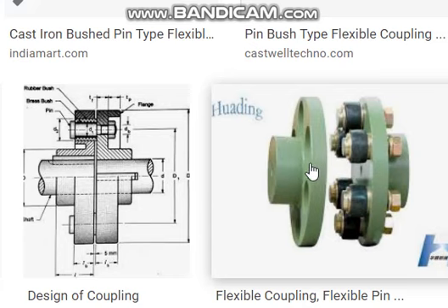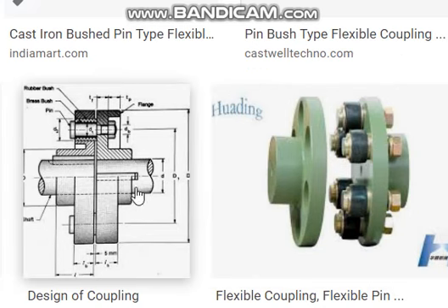This is another flange. In this, holes of larger diameter will be there. The pin will be fitting here. Okay, see here, this is the normal drawing which we draw on the drawing sheets. This is a half section. It is shown such that below the center line we are showing as though it is not cut, above the center line as though it is cut, and inside parts are seen. This is half section. From the outside if you look, you will see like this, but when you cut the inside, you will see the shaft extending up to this portion.